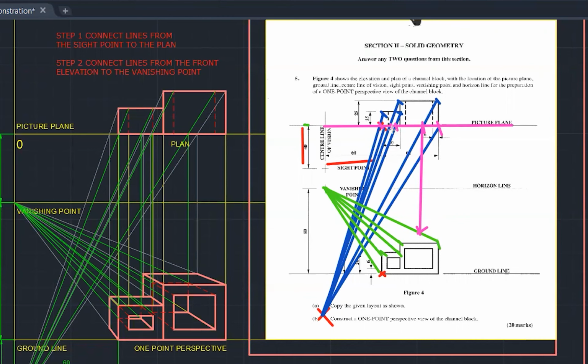Let's establish this corner here, and we pull this down. So this will cross in somewhere here, right? And let me just draw this shape now. That would take on a shape like that. And that would be the plan face that we have projected.